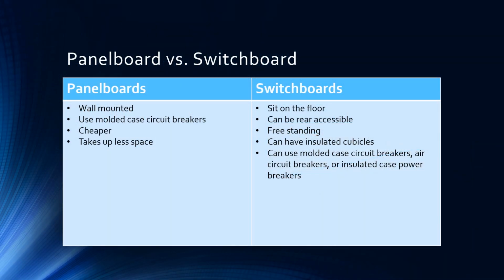Now, you can either have a panel board or a switchboard. They're pretty similar, but they do have some key differences. Panel boards are wall mounted, use molded case circuit breakers, tend to be cheaper and take up less space. And